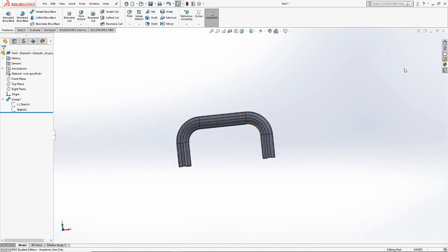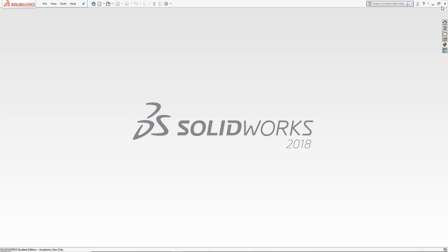So if you were trying to model a shape that had more complicated geometry than just a linear extrusion, the sweep is often useful for that. So that handle on the cup that we made in class last week, we could have done with a sweep. Doing it with a sweep would allow us to define maybe some softer edges so that the handle was more of an arc and less of a rectangular rounded edge shape. We have options with the sweep that we wouldn't have had otherwise. Let's try another example.